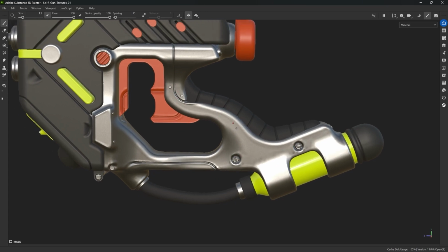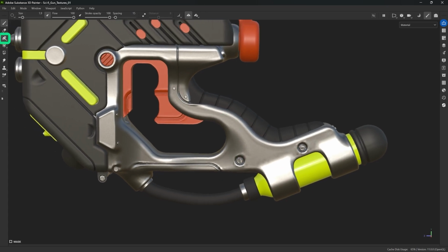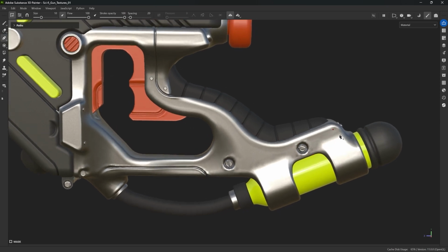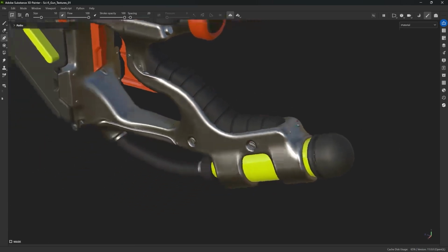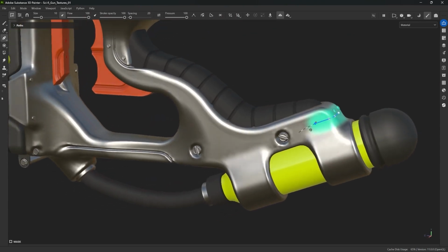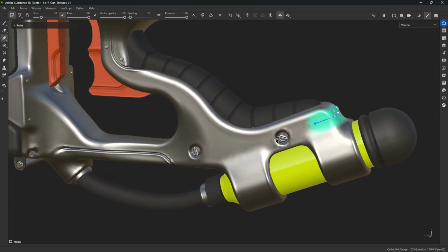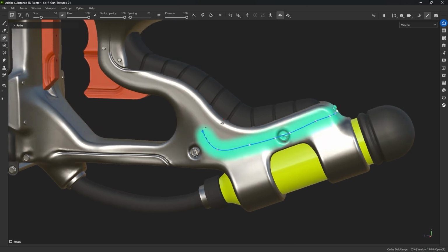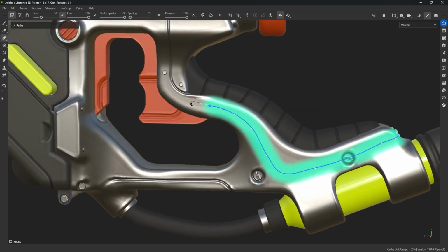For that, I'm going to go ahead and click on this icon, which is the path tool. The path tool allows you to use a Bezier curve or use points. So let's actually start here from the back. I'm going to click here, and I'm also using symmetry, and I'm going to click on those points. Don't worry about the size of this. I know this is not a panel, but I'm just going to go through this and show you an initial setup. All right, I think that works.